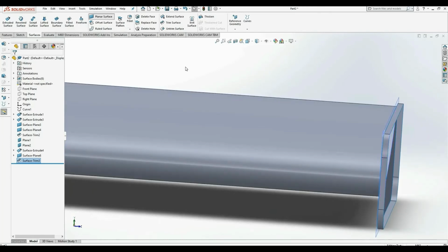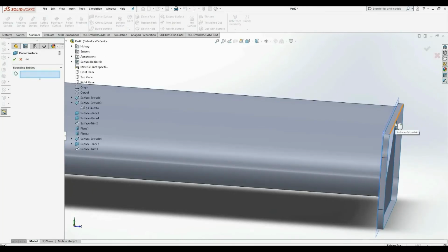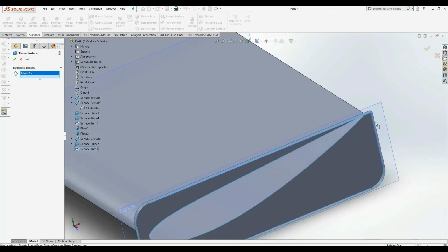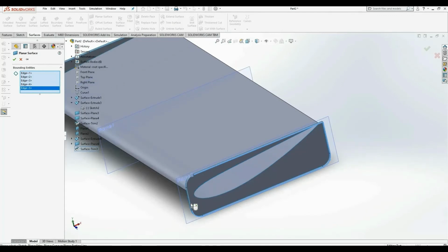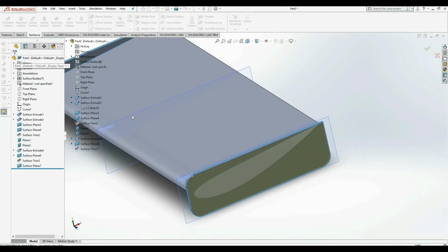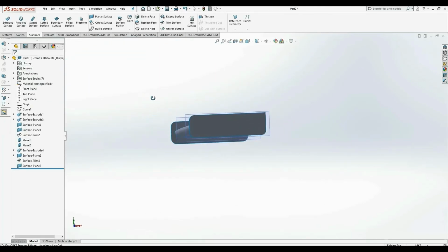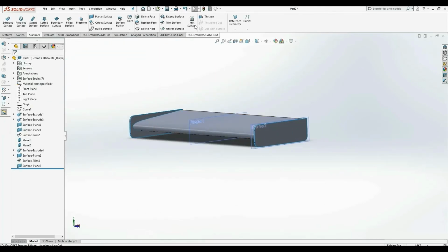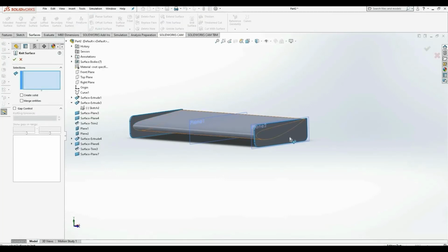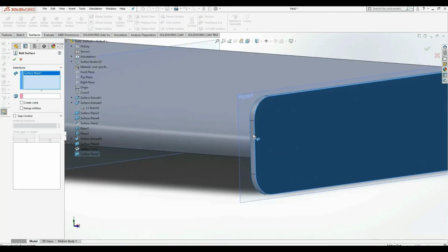We've got the extruded end plate profile, so if I add a boundary onto that section, that should be quite simple to create a solid version from knitting this together. We now get the yellow boundary, so we now have what should be a completely hollow representation of the aerofoil.